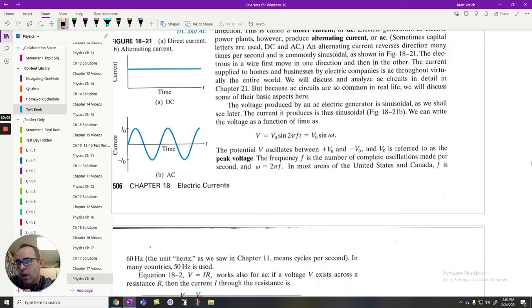When we start talking about things like average voltage or average current, we have a problem. Because when you look at, say, this point up here, say you're at 1, let's call it 1 amp. Down here, you're at negative 1 amp because you're going backwards. Well, when you start to average these currents over time, you end up with an average of 0, which doesn't help us mathematically. Everything's 0 all the time, but we know that's not true. So we had to have another way to modify and to understand the mathematics.